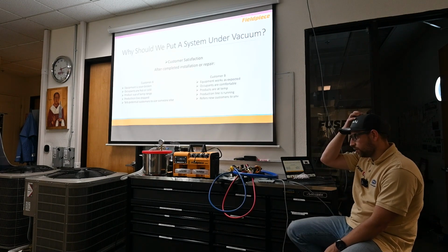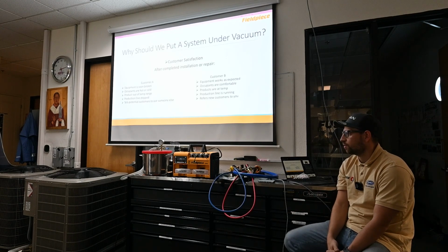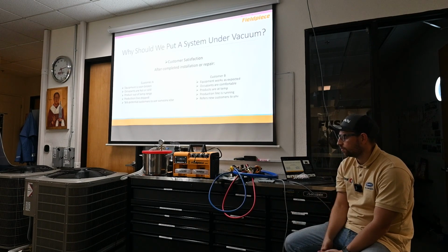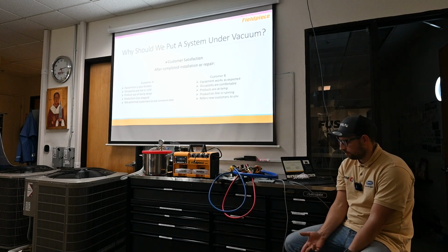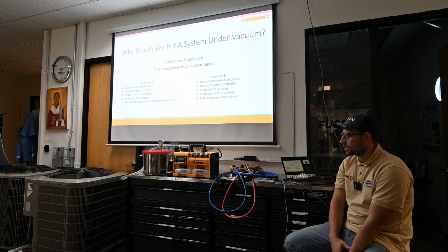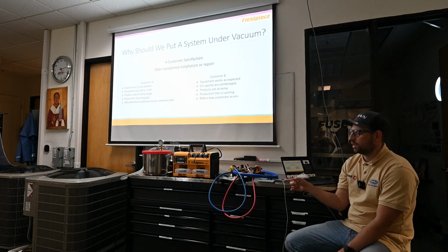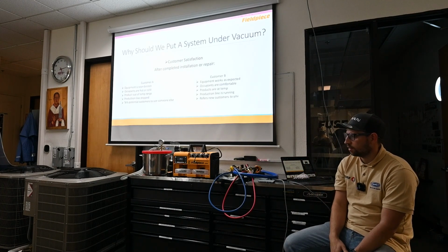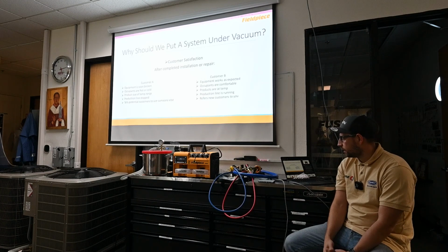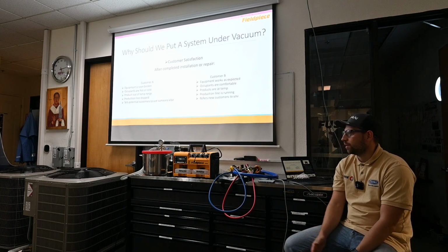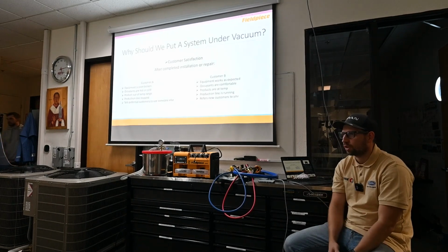What happens if you install a brand new system and forget to vacuum, and any air, water, gases or something like that remain, and you open the valve from the condenser unit? The system will start to work, but maybe after a few years the system will be broken.